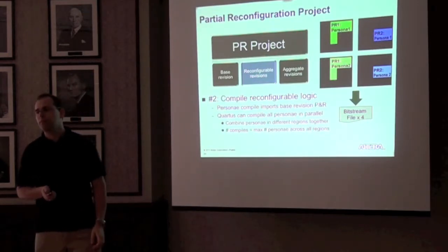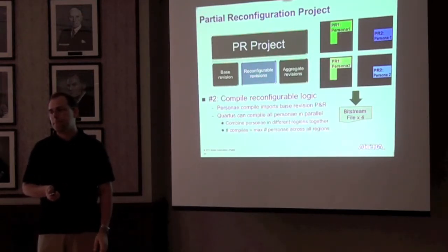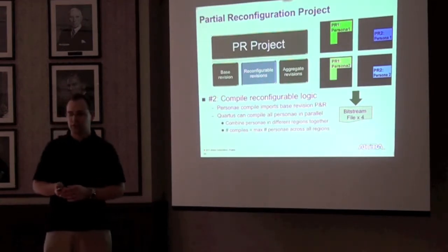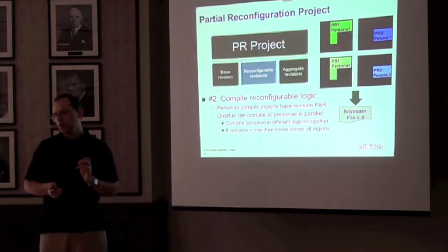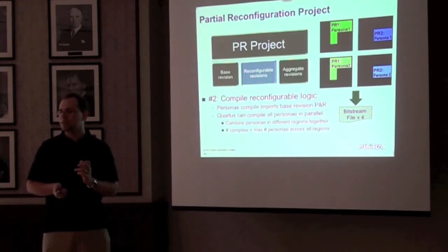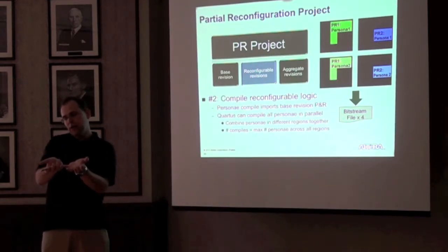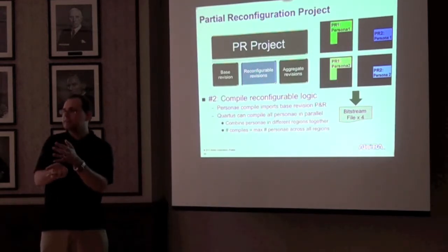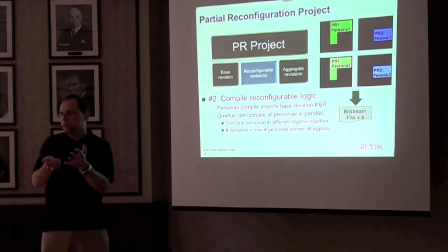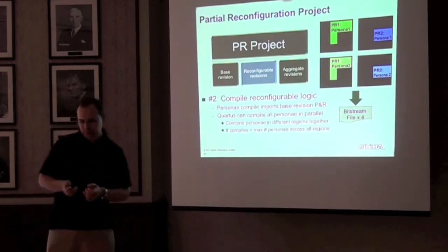Sorry, when you say compile them together, are you allowing optimizations across the two PR boundaries to occur? That's a good question. Are there optimizations across the PR boundaries? So not synthesis or placement. Synthesis obviously leverages the incremental compile framework, but once both PR personas are alive, there is some sharing of routing resources, and I'll talk about that later in the presentation.